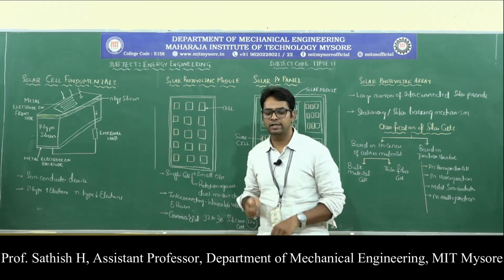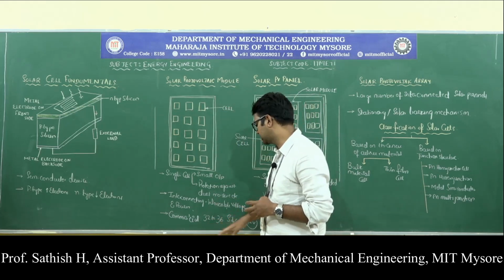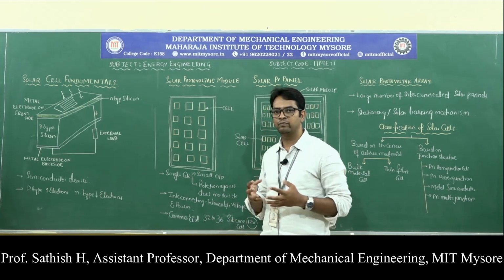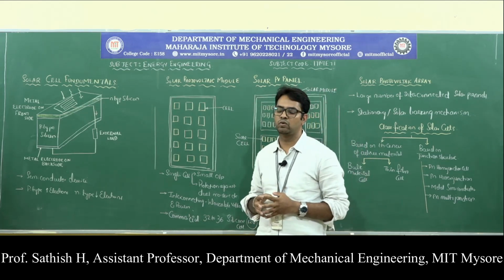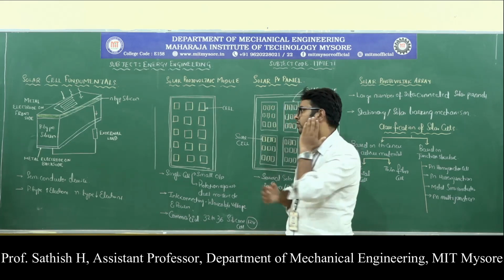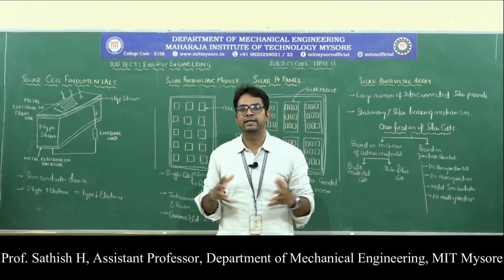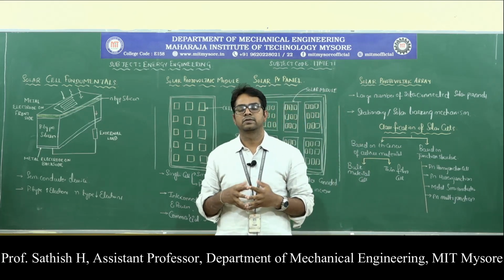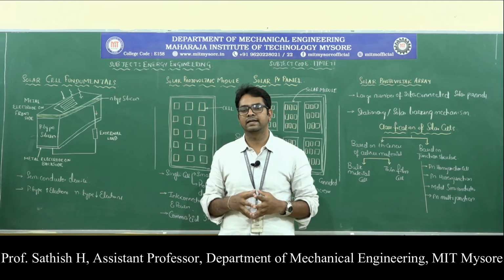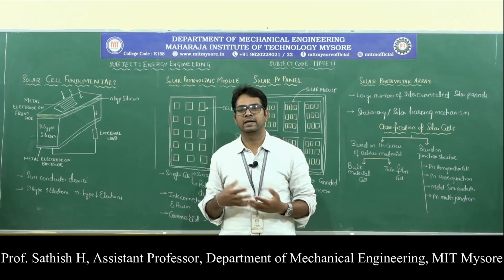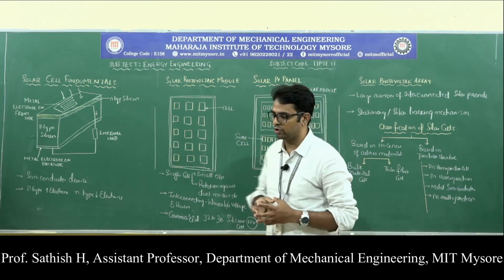The commercially used photovoltaic modules normally have 32 to 36 silicon cells, which can produce up to about 12 volts. That is the solar photovoltaic module we have. What we basically do is interconnect the solar cells, because an individual cell can produce very little power. By interconnecting them we can have a workable voltage as well as a workable power. So that is about the module.